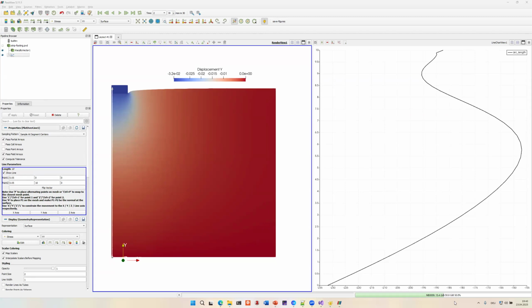So let's say you have a limited amount of information from field data, you have a grain size distribution, and maybe you also have 1 or 2 tests. You could at least make a rough prediction. You can estimate a set of parameters and then maybe identify areas where you sample more and then have a proper calibration. That would be the goal at the end. But currently it's pure optimization. So you feed in experimental data and you get out a calibrated model.